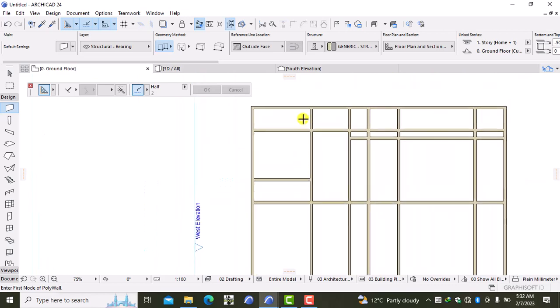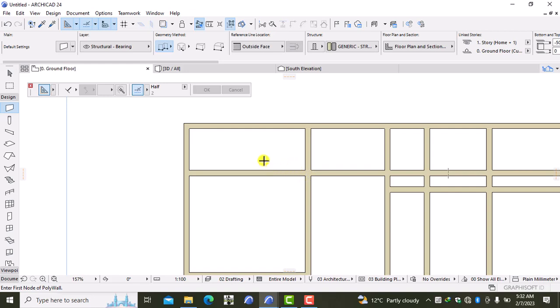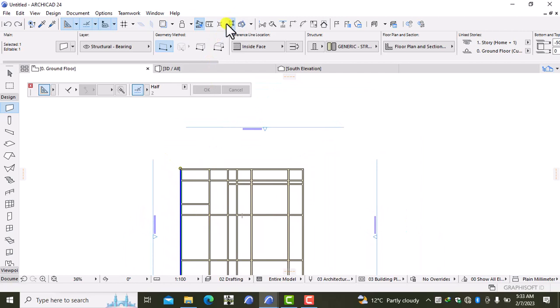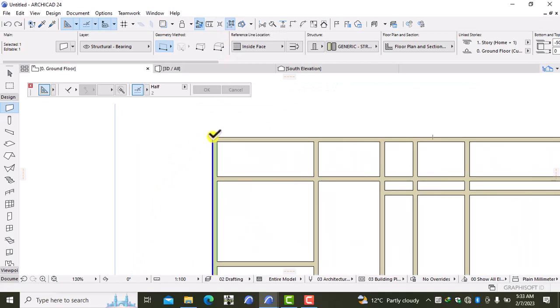Also I have another wall over here at a distance of 1000, but I can first edit this. Just hold on to the shift button, just drag this. So maybe when you are selecting your wall right over here, it selects all the 4 walls that we drew, the boundary walls. So basically what you have to do is suspend your groups. You come to this tab right over here, you activate it, and then you are able to select your walls as individual walls, as individual elements. So you can drag it like that.